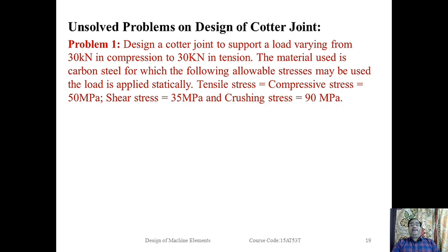The material used is carbon steel, for which the following allowable stresses may be used. The load is applied statically. Tensile stress is equal to compressive stress, that is equal to 50 megapascal.